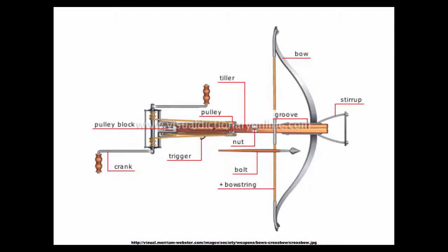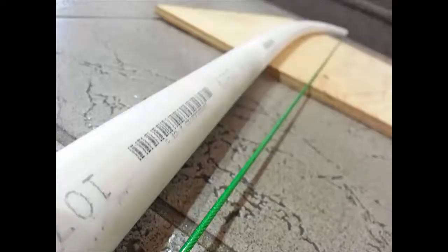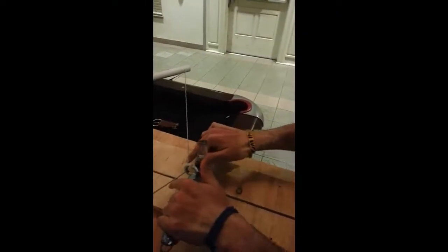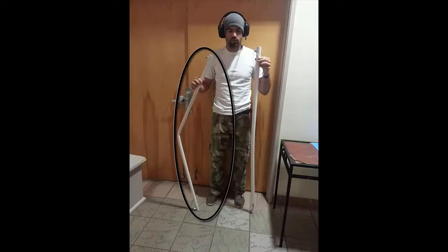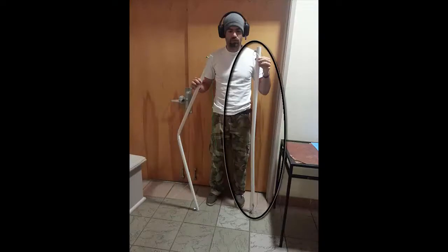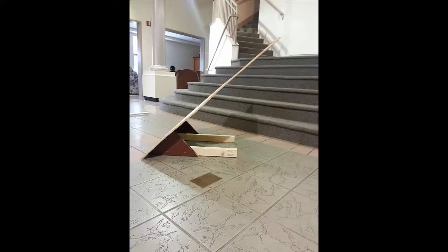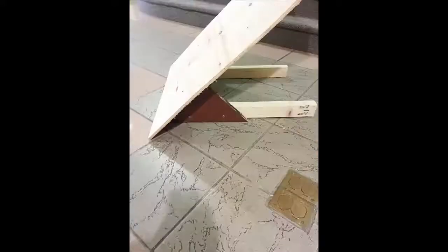Initial crossbow was made out of a 3/4 inch PVC pipe. When we were testing it out, we realized when we pulled too far back that it would just permanently deform. So to stop this, we went with a larger 1-inch PVC pipe, and we used a 1/16 inch wire. The original base was able to be angled because we thought that there wasn't going to be enough lift.